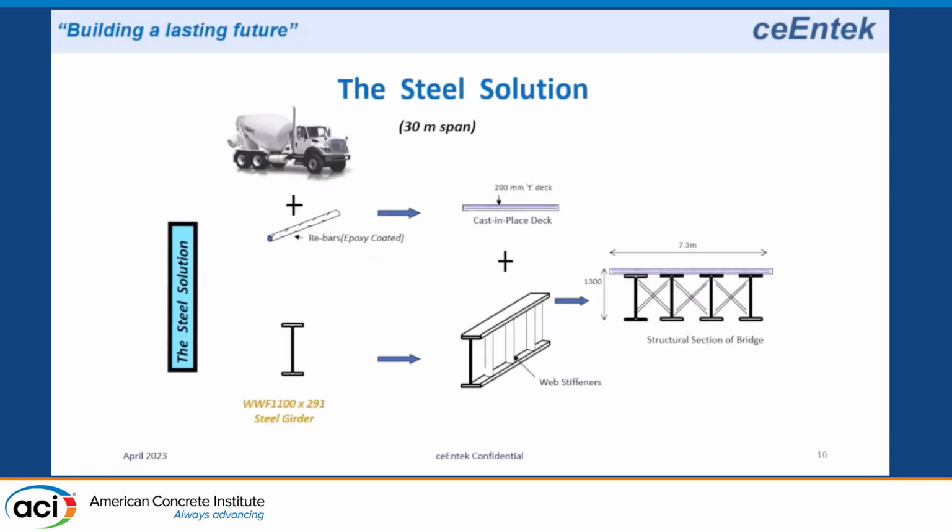And now compare that with a steel girder bridge. So it has a wide flange. This is the metric size, 1,100 millimeters by 291 kilograms per meter. We're going to have 4 of those. We're going to have steel diaphragms for load distribution. I should have mentioned that the precast girders have concrete diaphragms for load distribution. We'll have the same deck, cast-in-place deck, ready mix, rebar, and cast-in-place. Again, 100-foot span, 25-foot wide, and that's another conventional bridge of this type. And this again is the VDOT design.